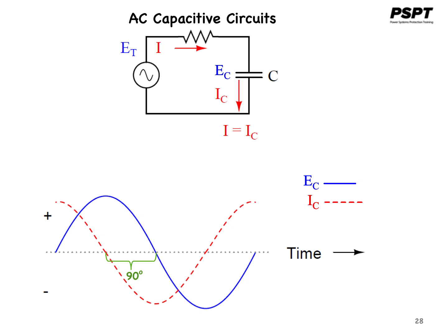This results in a voltage wave that is 90 degrees out of phase with the current wave. Looking at the graph, the current wave seems to have a head start on the voltage wave. The current leads the voltage, or the voltage lags behind the current.